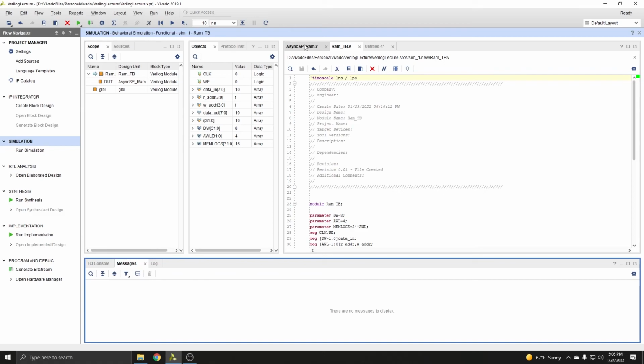But if you're ever writing Verilog, you need to keep this in mind: whenever you perform arithmetic operations like addition or multiplication, or even potentially subtraction, the bit width will and can grow.